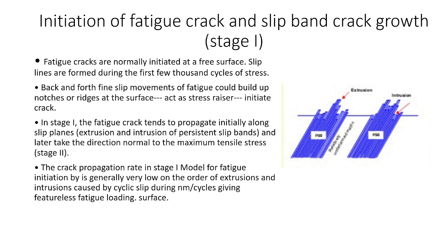Okay, it's a stage of plastic deformation. It cannot be recovered. In stage 1, the fatigue crack tends to propagate initially along the slip planes, through extrusion and intrusion of persistent slip bands, and later takes a direction normal to the maximum tensile stress. So the crack propagation rate in the stage 1 mode of fatigue initiation is generally very low. So the initiation crack length grows very slowly.